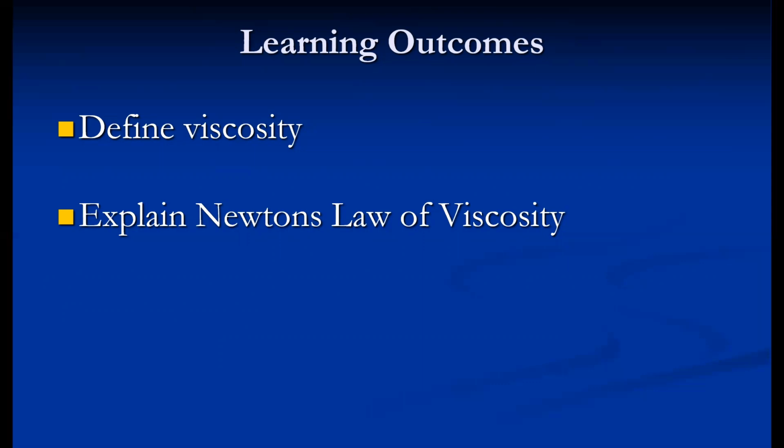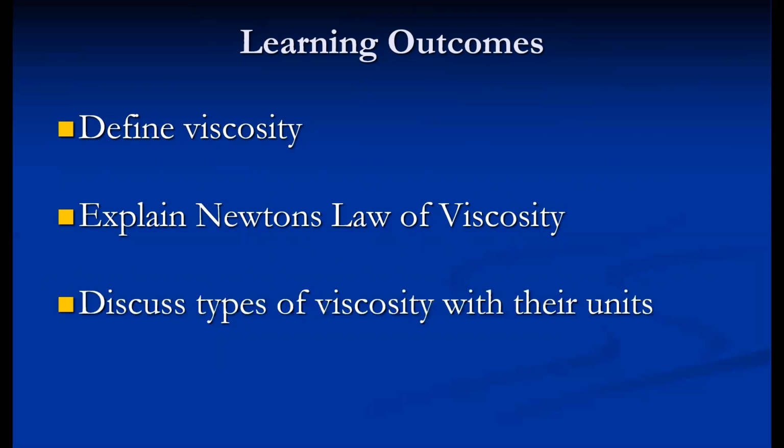So either of these conditions should be satisfied: the fluid is thick, the distance between two surfaces is very small, or the speed is very low. Either of these three conditions must be satisfied in order to apply Newton's law of viscosity. You should be able to apply it while solving problems in coming lectures.